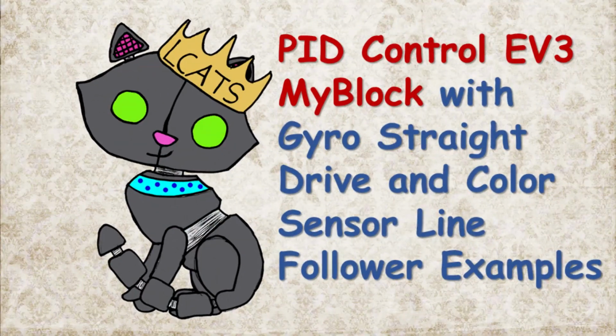Hey guys, in this video I'm going to show you how to program a PID Control MyBlock, how to use it with the gyro sensor to drive straight, and how to use it with the color sensor for line following. PID stands for Proportional, Integral, and Derivative. Having the PID Control MyBlock makes it easier to use PID Control in other programs.